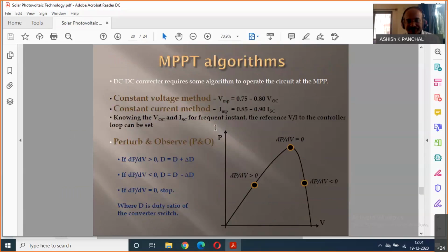So of course, we need to know that the panel, converter and load have to know whether the condition has changed. If the condition is changed, then the PV voltage has to be adjusted to extract maximum power. Now suppose after some time the condition changes again, so you adjust the duty ratio of the converter, and power is generated without losing.